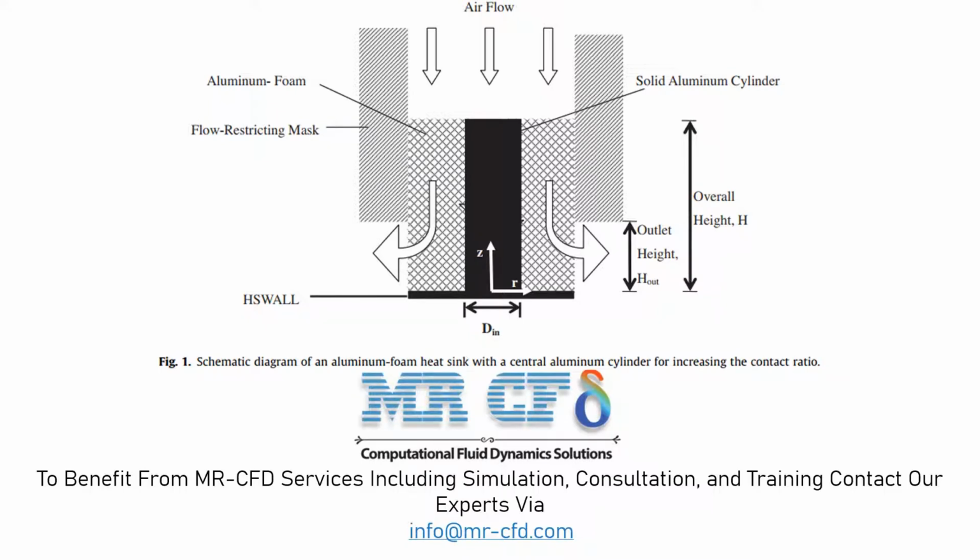The airflow enters the chamber vertically and downwards from the upper section and exits horizontally from the side sections at the bottom of the chamber. Inlet airflow is assumed to be developed flow, hence the height of the cylinder is assumed to be relatively high. The inlet airflow has a temperature of 300 Kelvin and has variable velocity. The purpose of this problem is to investigate the value of the Nusselt number in the porous region of the chamber in different Reynolds numbers.